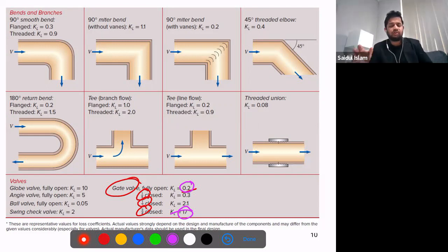we know that a lot of inserts and all those arrangements I said earlier, like the valve, the inlet, outlets, the contraction, expansion, all are responsible for the minor loss. But the gate valve, we will get the most significant minor loss from the valves. And now you see, if you have a pipe with 3 valves in a very short distance and it's almost closed, then you can see how significant the minor loss will be. So it will be then a major loss, and maybe it will be even higher than the pressure loss.